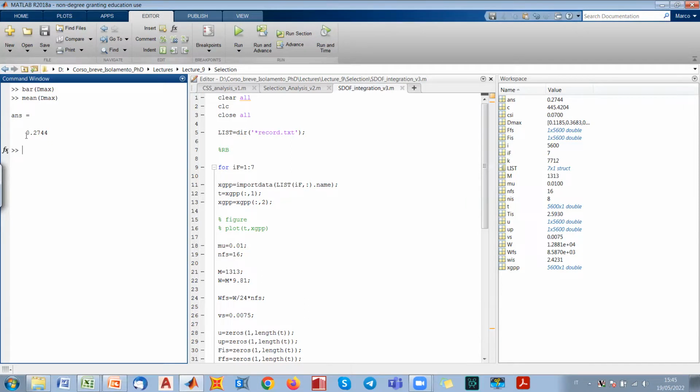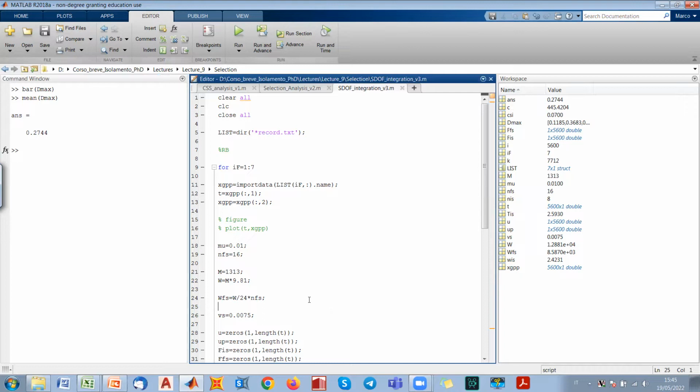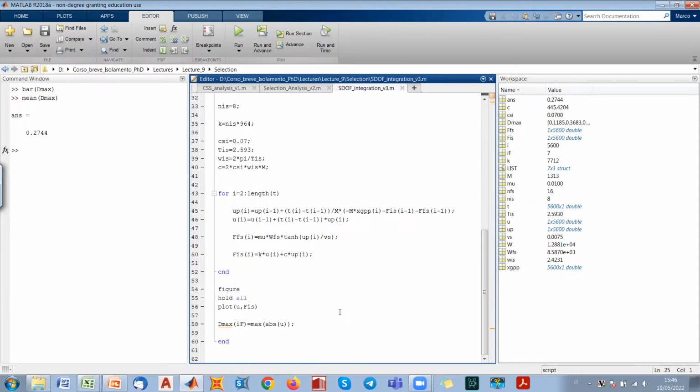And again we have this difference which is lower than the design value of displacement, simply because again here we have the flat sliders, so we are increasing the dissipative capacity. And actually here the influence is much higher in comparison to the lead rubber bearing case, just because the rubber bearings, so the isolation system, has a very low damping ratio for design. So this means that also the equivalent viscous damping associated to the hysteresis provided by flat sliders is small, but maybe it is more comparable to the damping ratio of the isolators in this case rather than in the case of lead bearings. So the influence with respect to the additional dissipation capacity of the devices is much higher in comparison to the previous case. So I think we are done for this.